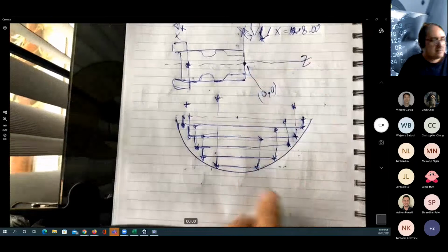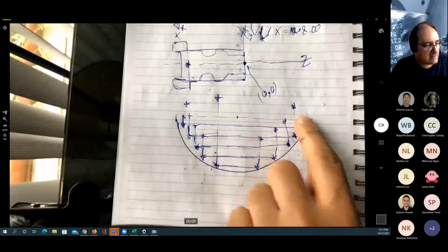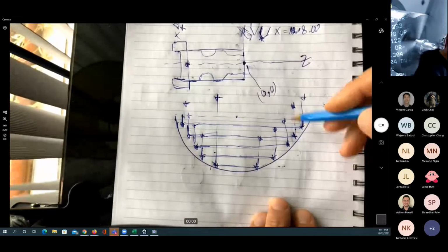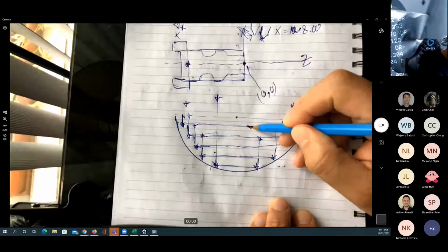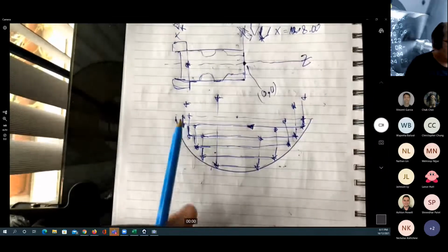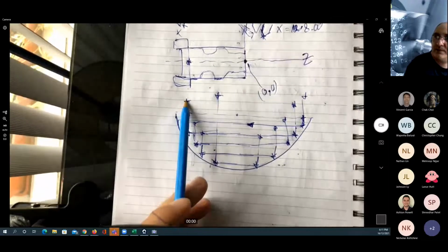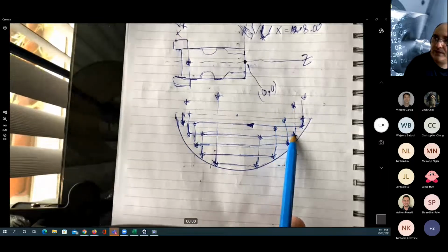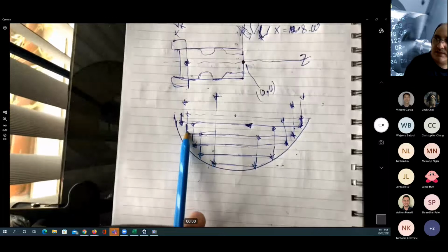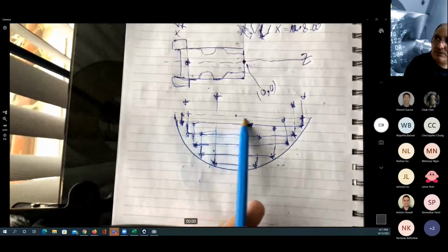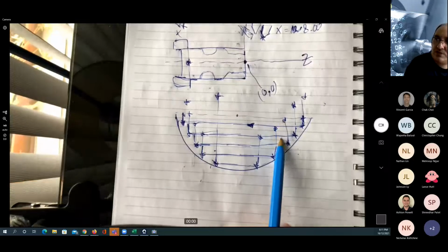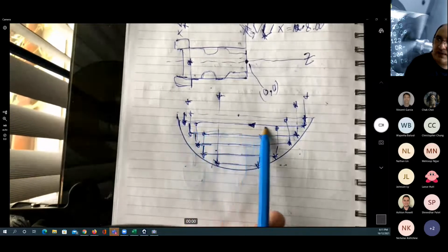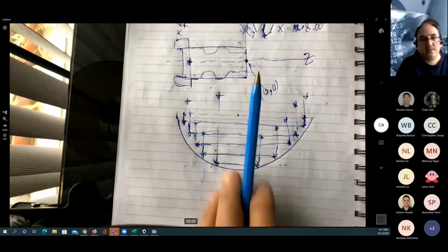and 20. So we're going to start from here, going to that depth, moving the cutting tool in this direction, again to reach that point. We leave the part, we travel back to the next point, and we set the depth of the cut, G00 once again here, G00, G01, G01, G00, and continuously until again to remove these layers.